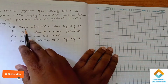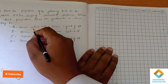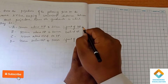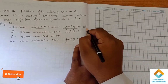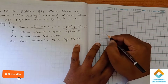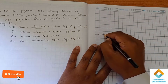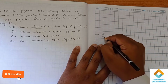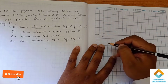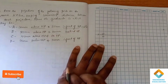Point A is lying 30 mm above HP and 35 mm in front of VP. So above HP and in front of VP means it is in the first quadrant, right? In the first quadrant, for your reference I will write: VP will be above the X line and HP will be below the X line. After drawing the projections we will erase this. So 30 mm above HP and 35 in front of VP, it is in the first quadrant.